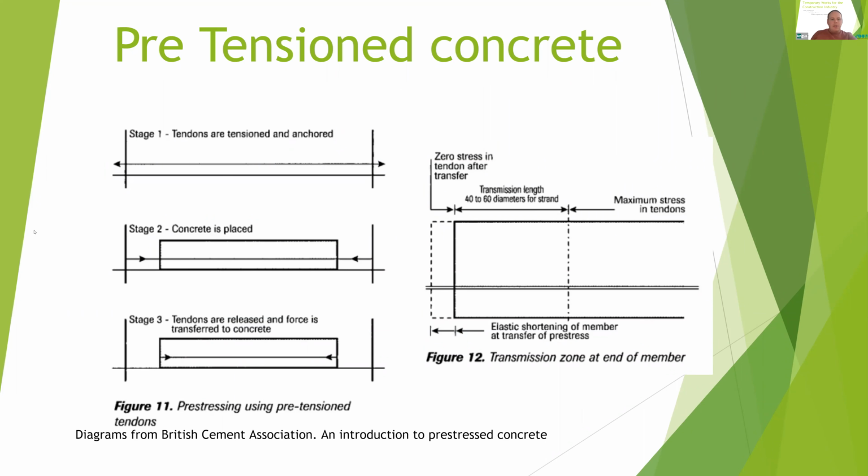So as I mentioned there, this is how you'd go about doing it. With the pre-tension structure, you need to have a formwork in place, and you need to have some big, heavy anchor points either end of the item you're trying to cast. This is why this is generally done off-site. Or if you have a lot of similar beams, it might be worth setting up on site to do it yourself. Though generally today they're made in yards across the country and shipped where they're required.